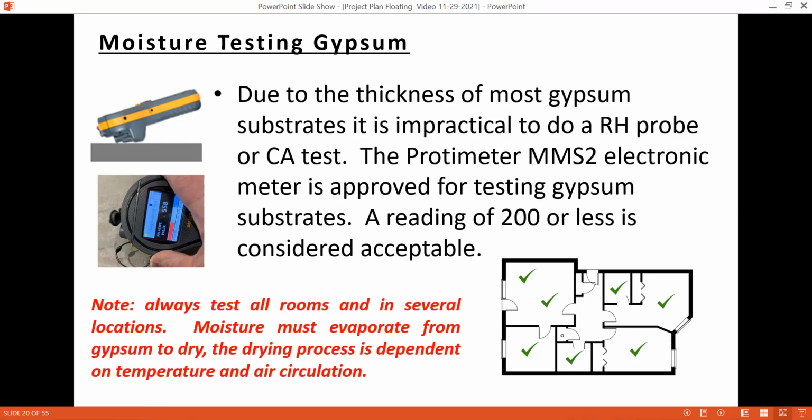Gypsum drying requires heat and air movement. The moist air must be ventilated out of the building. This can be accomplished by cracking windows open or venting outside. Gypcrete can be dry in the living area and wet in the bedroom area. Many times, gypcrete is too wet to install flooring several weeks or even several months after the pour, if proper heat and ventilation were not provided.